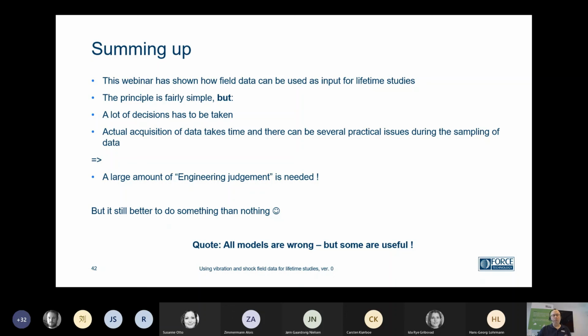I can compare from real life to testing, or I can compare different shocks in real life. Then I have to know some information about the resonances of the products. For a mechanical test guy like me, I use a lot of time to measure resonance in a product, because once I know the resonances of a new product, I can calculate a lot about how it will react in different environments. But that's shock response spectrum.